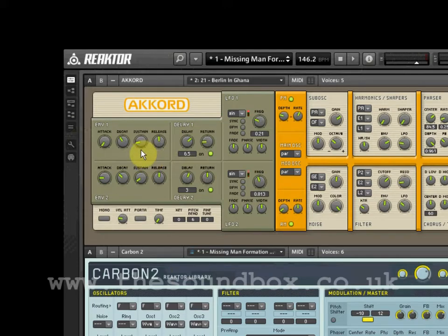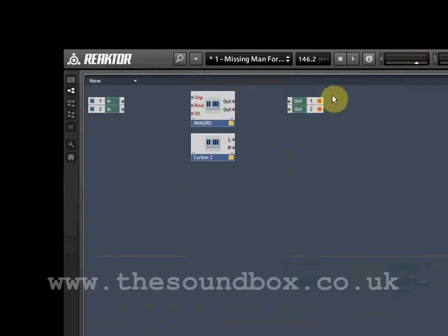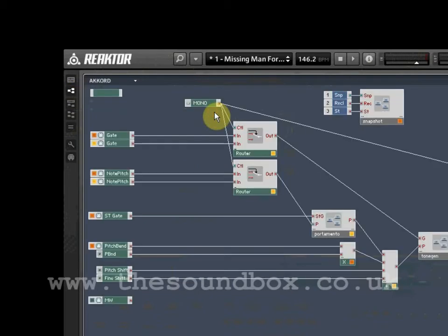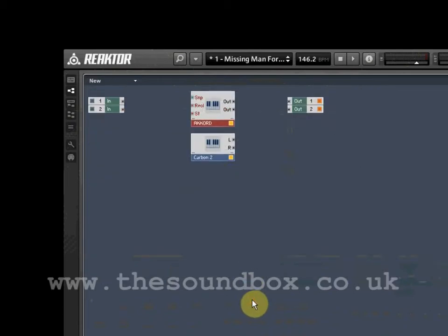Let's go back to the structure view. We have different layers in the structure of our instrument. The audio outputs are usually found on the highest layer. If we double-click on Macro, we move down a layer and view the components inside. By double-clicking on an empty space within that macro, we can move up a layer.